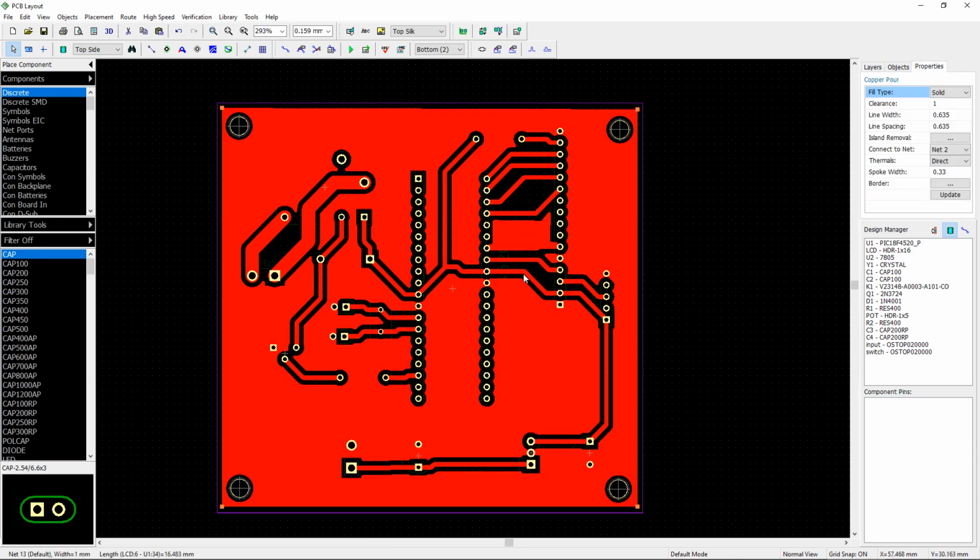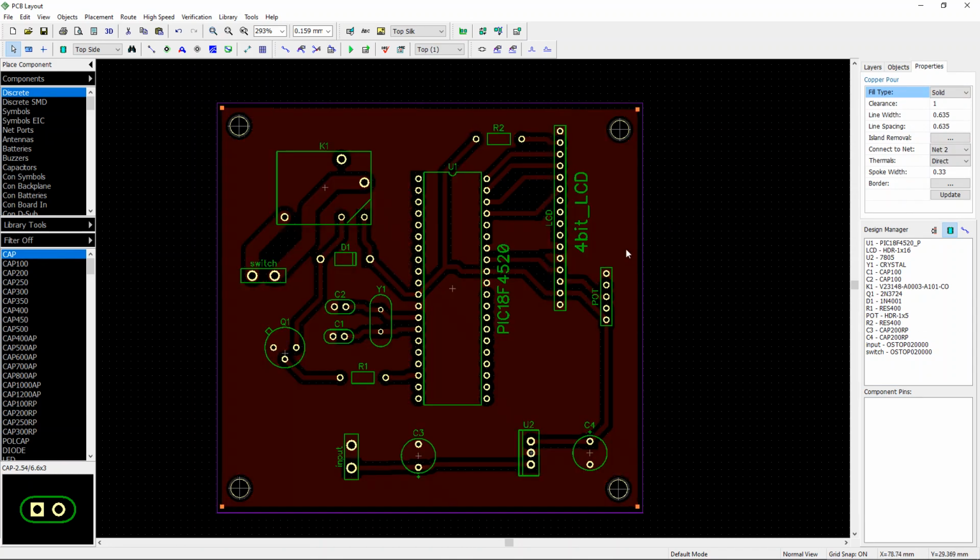So that was an illustration to show you if you get to such a situation whereby you are forced to do that. But apparently, because we chose the pins of the microcontroller in such a way that it will be less complicated, that is why we ended up having this. So if by any chance that happens to you, because there are designs whereby you actually pick the right pins of the microcontroller, but just because the components are too many, there are going to be conflicting traces, and you are forced to go through the jumper wire method. That's still fine, but always try to make sure that you don't end up there.